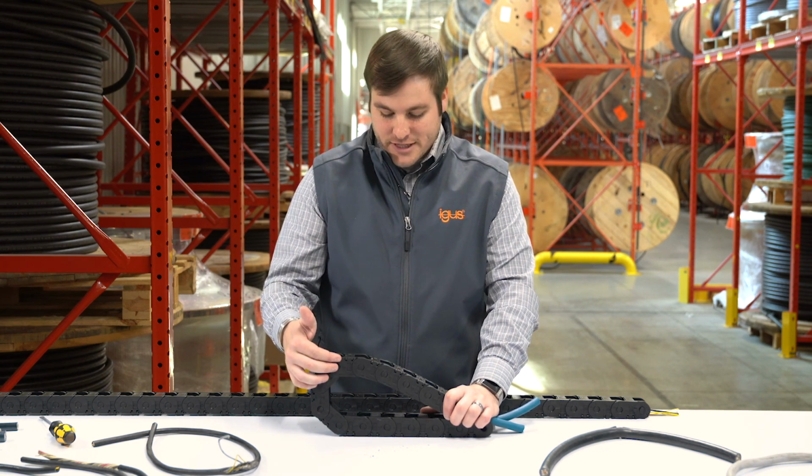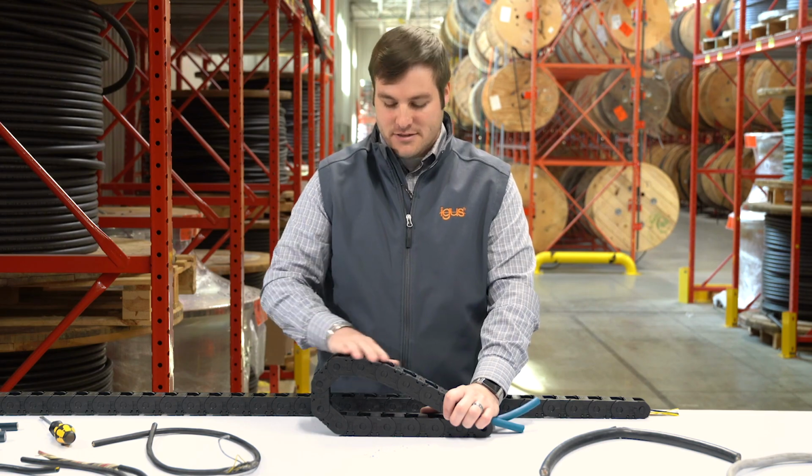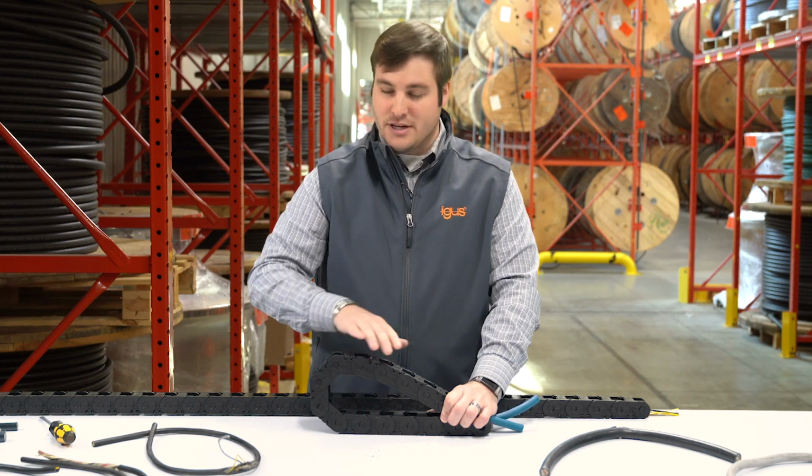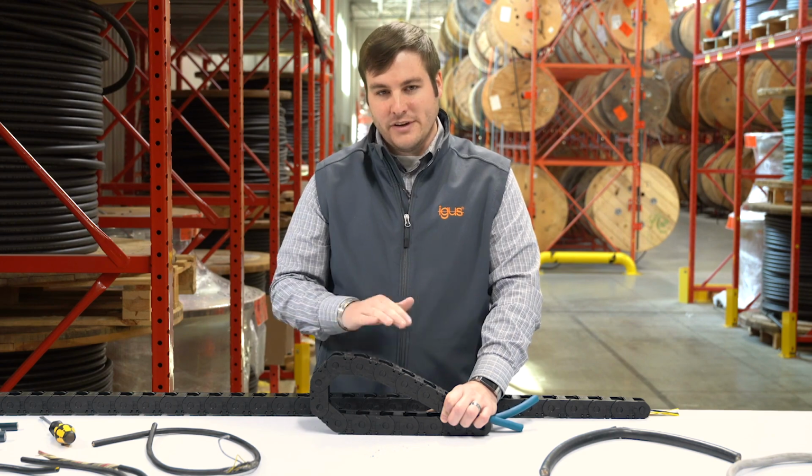The final failure type that we see in outer jackets is jacket abrasion. Now in this particular example, we can see where the jacket is actually abrading against the cable carrier. You can even see that there's actually some of the material that's abraded off of the outer jacket when used in cycling back and forth in an E-chain on the table here, because this particular cable probably isn't suited for use in a moving application.